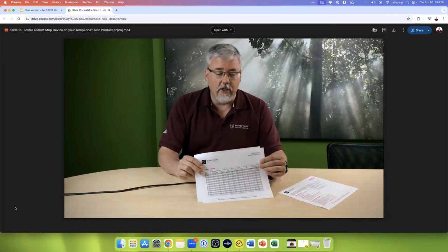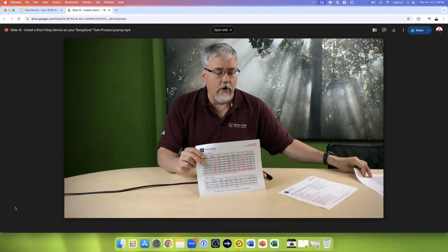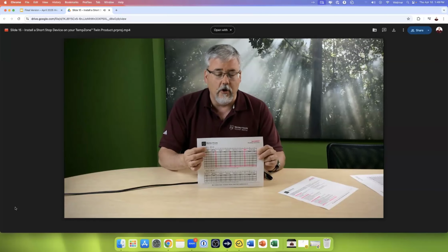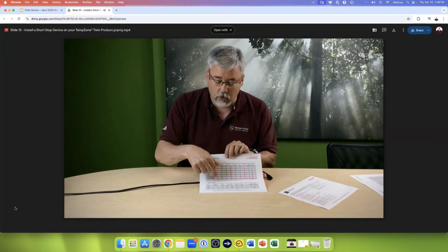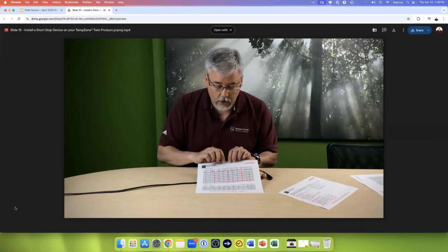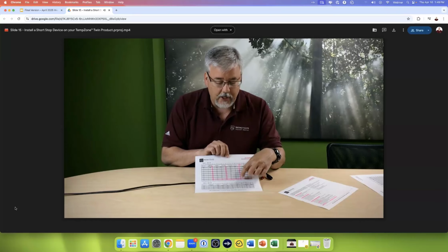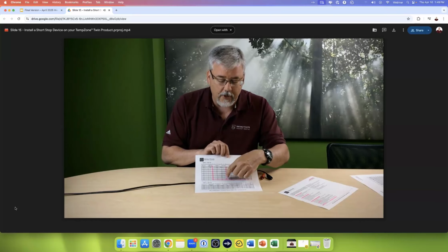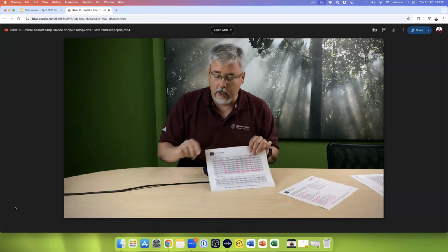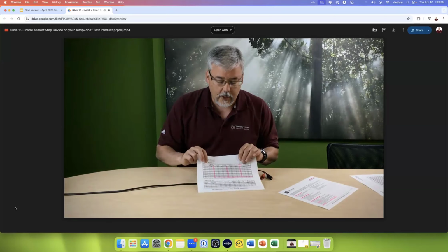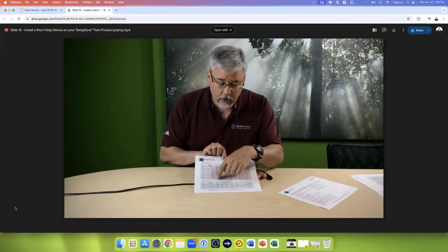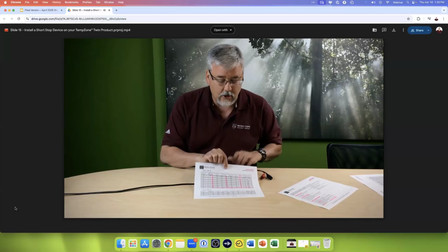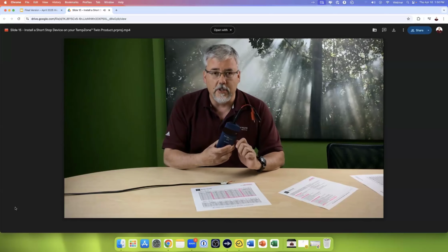So table 1 is a 120 volt table, so we get rid of that. We don't need it. So all of our information is going to be here on the 240 table. On this table, you need to find out what size roll you have. You also need to find out what the VOP is for the particular roll, and then it will tell you how many feet are in that roll, including the cold lead. So let's pretend that we have a very long roll, and that is a 76-foot roll. So we need to look over here and find the VOP. That is 62. So we need to set the VOP on this unit to 62.